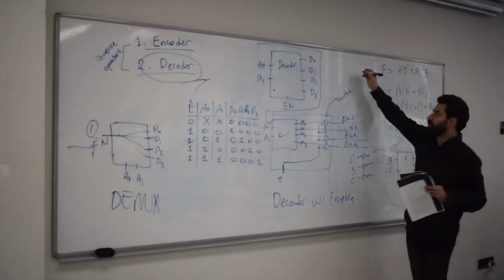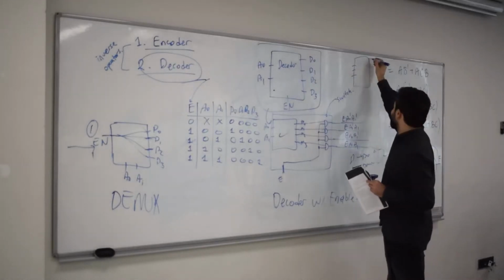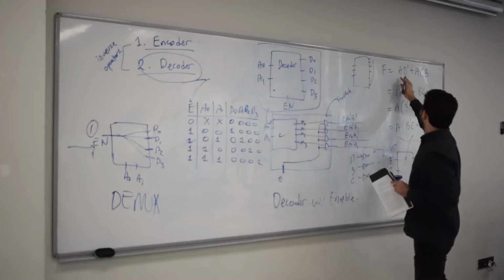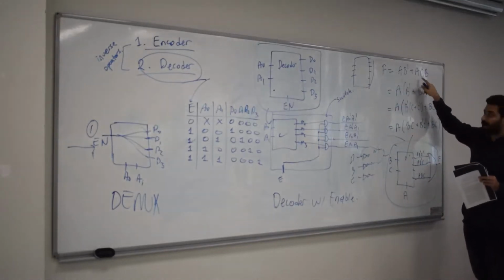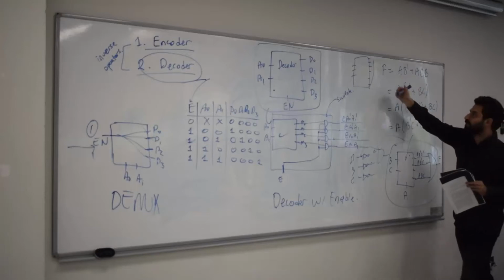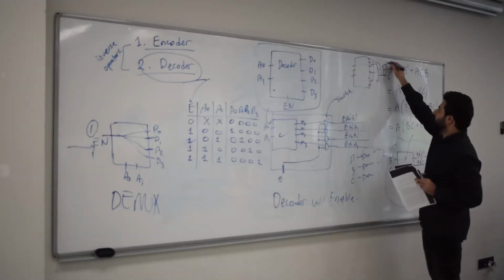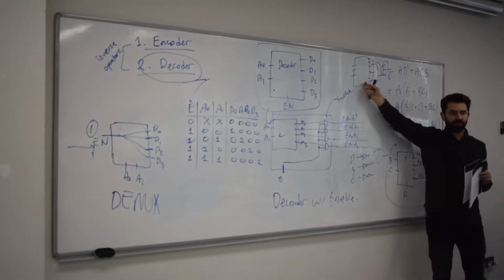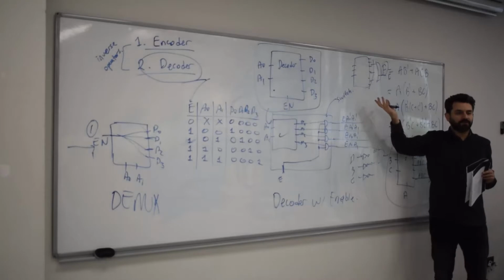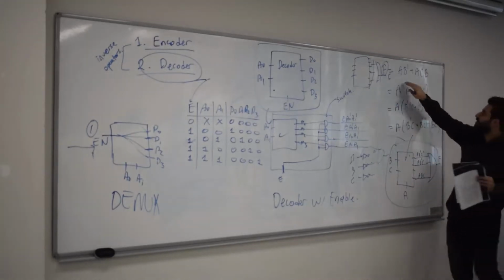Instead, what would you do? You would use a 3-input decoder and 8 minterms, and then figure out the minterms here. For example, you've got 1 minterm here and 2 here. So there are going to be 3 of them all together to create that functionality. Okay? But this would be a bigger decoder because there is no enable input. Here, we've got an enable.